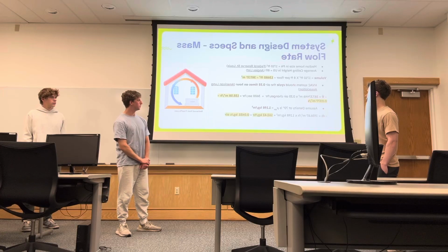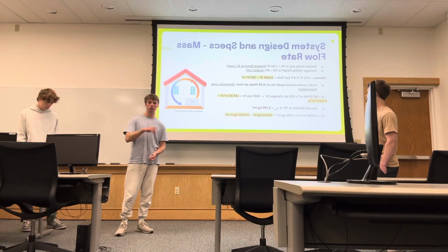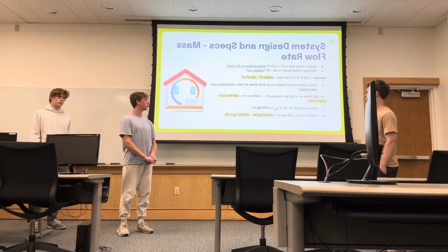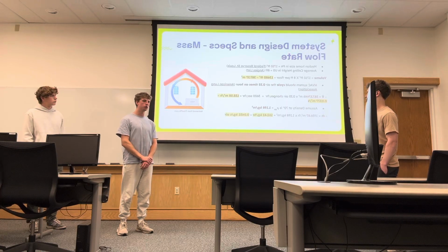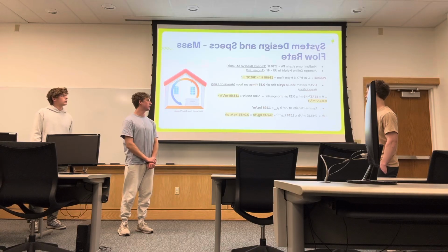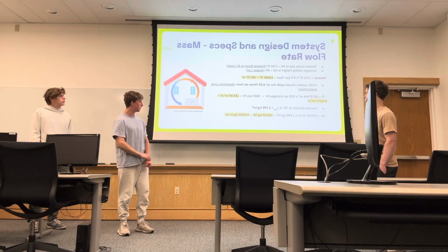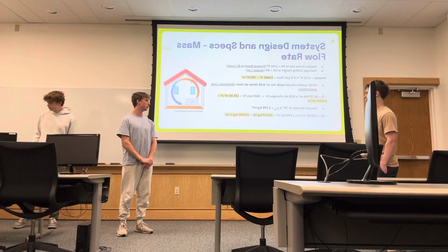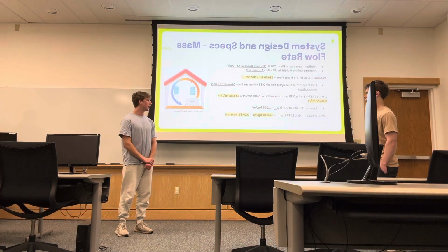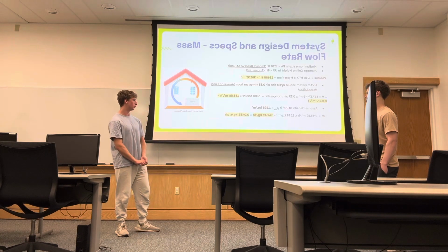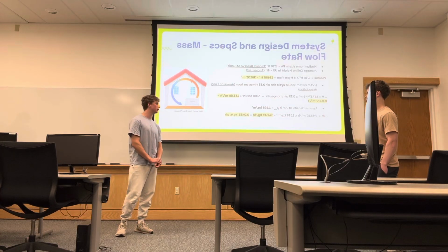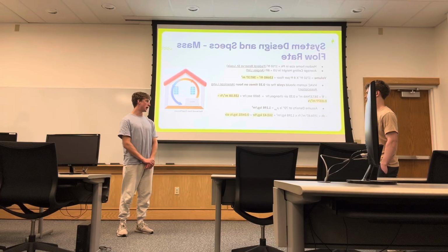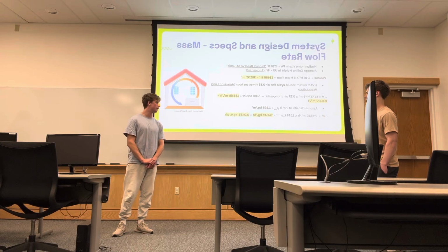According to the American Lung Association, HVAC systems should cycle air at least 0.3 times an hour, which equates to about 2.8 hours for each air change. Using that math, we found the volumetric flow rate to be about 135 cubic meters an hour, or 0.037 cubic meters per second. Using our assumed temperature of 70 degrees inside the house, we found the density of air to be 1.198 kilograms per cubic meter. From that, we found the mass flow rate to be 162 kilograms per hour, or 0.045 kilograms per second.